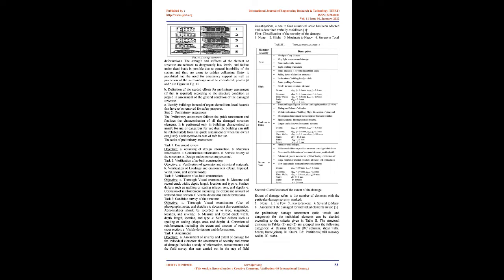An initial visual examination has shown that the original capacity of the building has not decreased and that no major hazard is present and no observable permanent deformations of the structural, non-observable or slight structural damage. Minor non-structural damage. Fracture in non-structural components of the structure, such as windows and doors. Use and occupancy allowed, except in areas marked area unsafe, indicating the presence of some local hazard. Photos 1 and 2, in Fig.